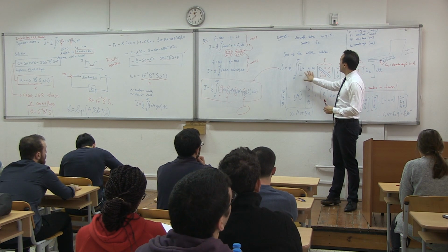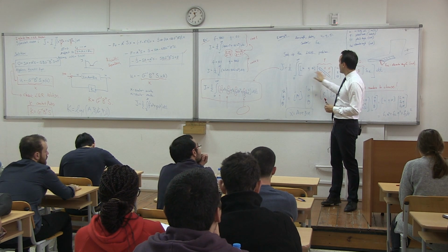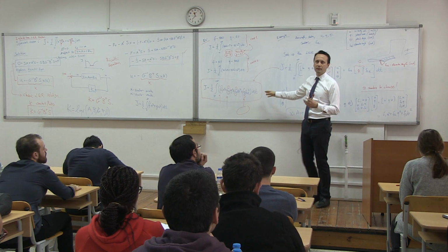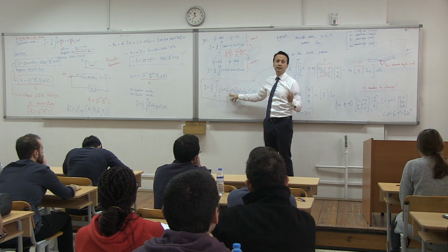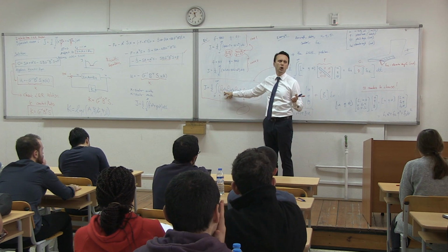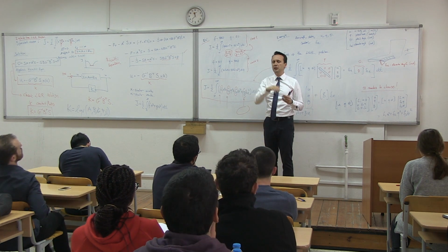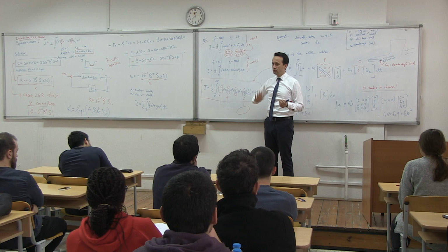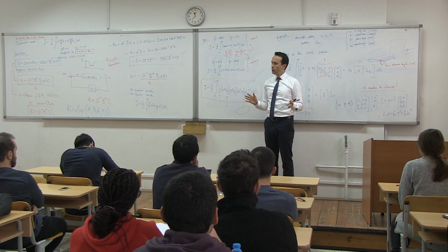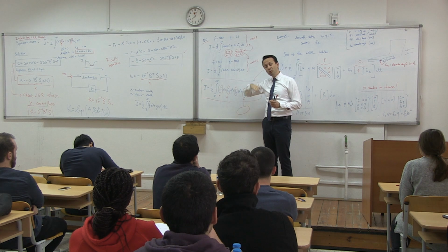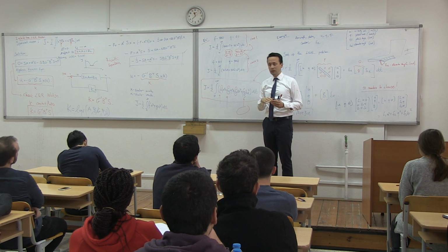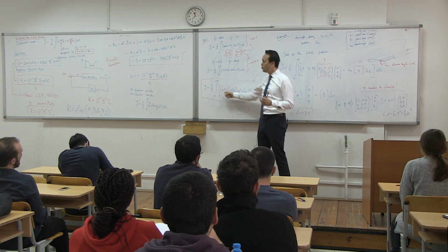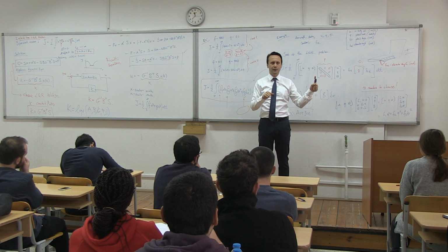Another thing is, of course, you need to understand the physics. If you don't understand the physics, you cannot make the right choices over here. What is more important? Why do I not want this to move a lot more? Well, first of all, U is slow, right? Changing the velocity of an aircraft is not very fast. Changing Q can be quite fast. So what is more important to the problem? Well, I don't want the Q to change much. If I know that Q is not changing too much, then I know U will not change too much, as long as the throttle is constant.